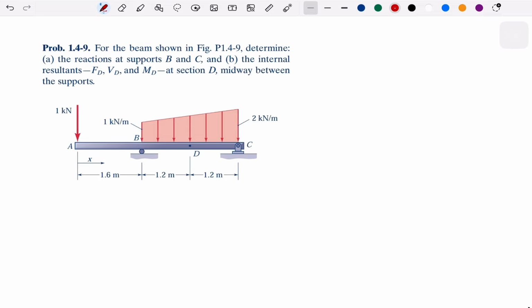So of course, if we can see all the pins, then we can define the resultant or the reactive forces. But before we continue to find the axial forces, the shear, and the moment at B, we could define this distributed force first.